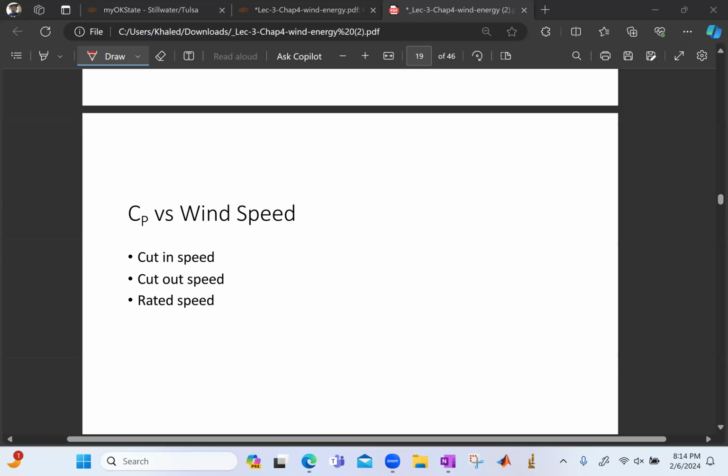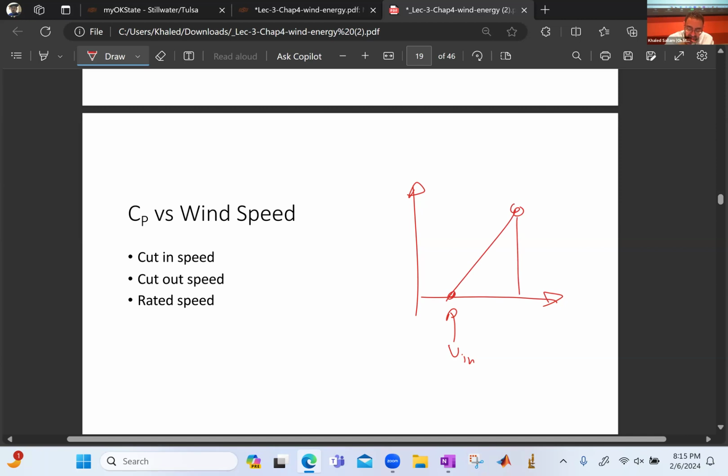All right, I think we should start. So we said that the turbine will have those characteristics, this curve, which basically says you kick in at V cut in, and then you will rise, not really in a straight line, but more like a curve, until you get to V rated, and then you will continue until V cut out, and then after that, you stop making power. So this is P output. Okay, so this would be P rated.